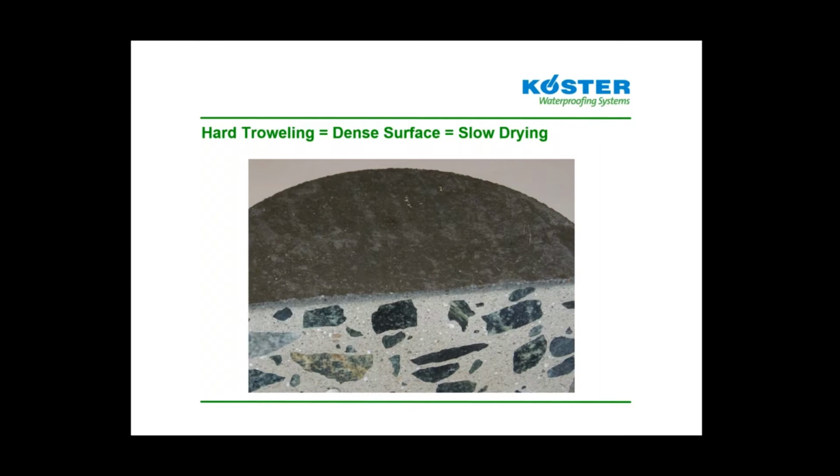This treatment does produce very hard, flat, smooth surfaces. It might be appropriate for some warehouse floors and other applications, but it is very unnecessary for interior floors that will receive adhered floor coverings or adhered coatings, because it is so hard to work with and it doesn't accept most flooring materials and bond well at all.